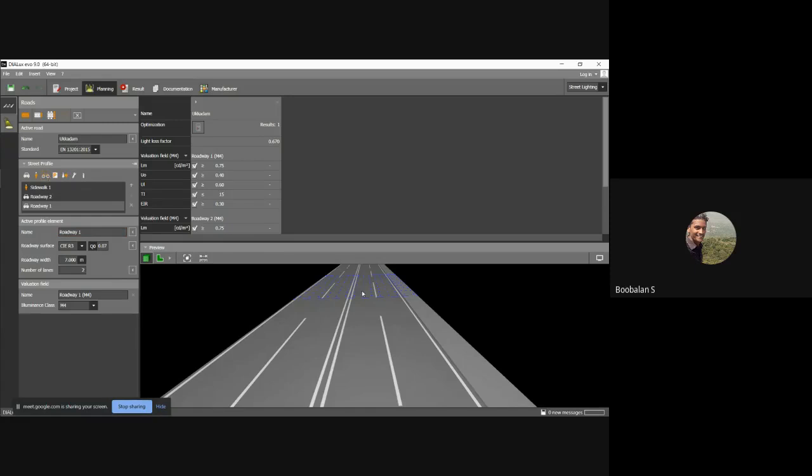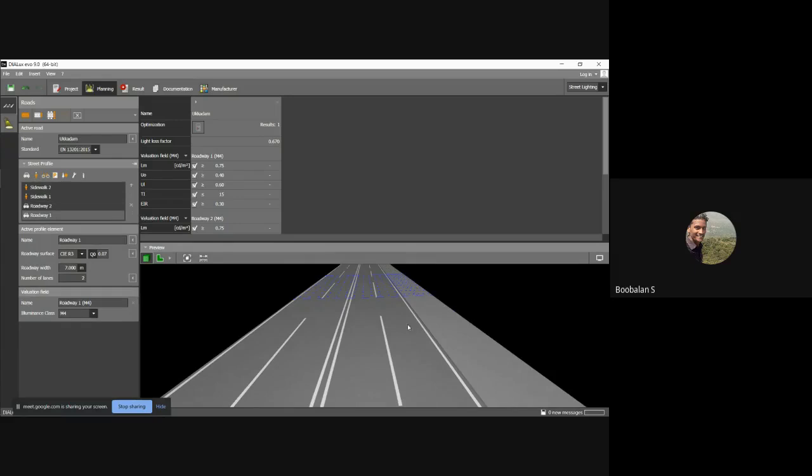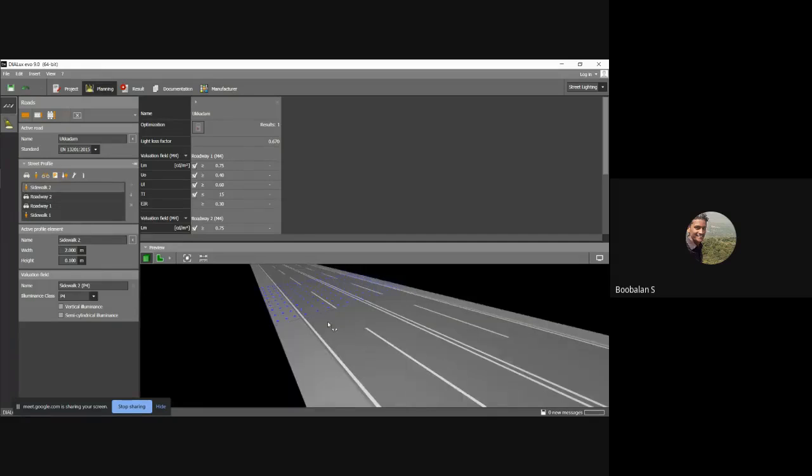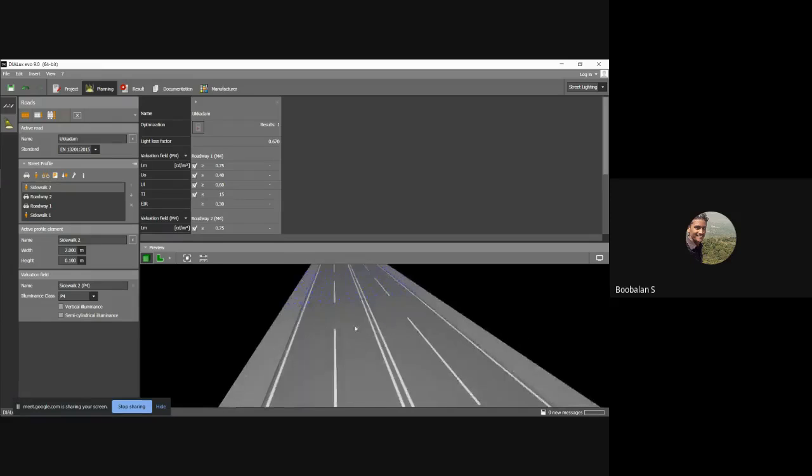And I'm going to add one more pedestrian path on my right side. Now I'm creating one more pedestrian path. But additionally, it is getting created in the same place. But if I want it on the left side, then look here, there is an up and down arrow mark, you can change it. Up and down arrow mark. You could see the sidewalk moving. Now the sidewalk will be changed with the help of this. Select it, and there is an up and down arrow mark here; if you change it, it will change. So now we have two roads, right?